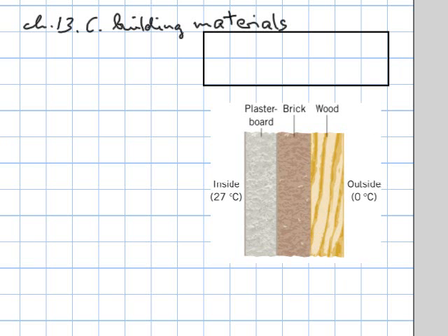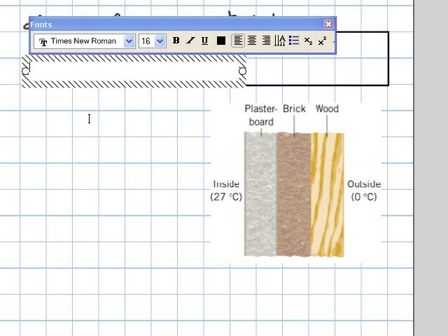Okay, I will not do the problem the way it's written out, and when I teach this in the classroom I always say that I'm not really interested in what the temperature is in between here, but what I'm interested in is how well these 3 sandwiched together insulate. So overall, I'm going to calculate the so-called resistivity or conductivity of these 3 sandwiched building materials.